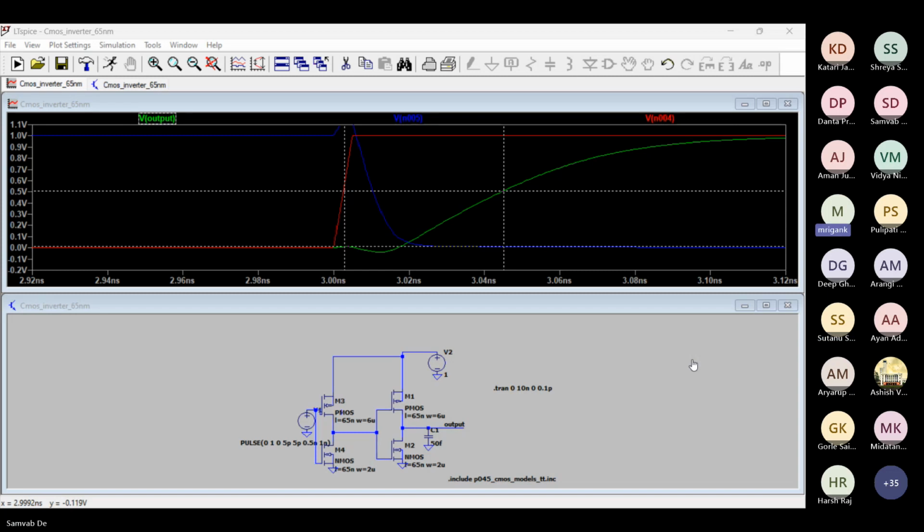In the small signal model of the MOSFET, is there any drain to source capacitor? You have forgotten the small signal model of MOSFET. So there is no drain-source capacitor. What are the small signal capacitances present in this MOSFET? Gate to drain capacitance will also be a factor determining the time.